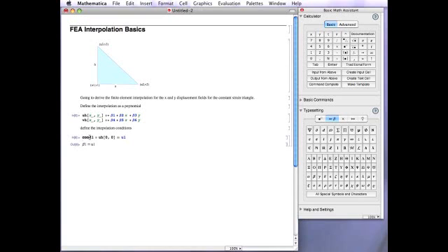All right, so we have other conditions. We can cut and paste. And now I can use return to put multiple expressions in one command block. Let's do condition 2: the y displacement at node 1 has to equal the nodal unknown v1. And then we can just copy and paste this for the other two nodes.